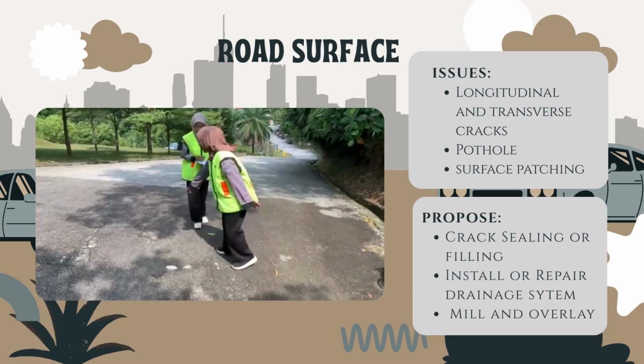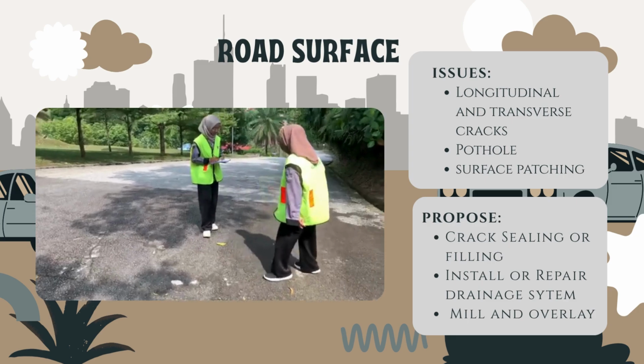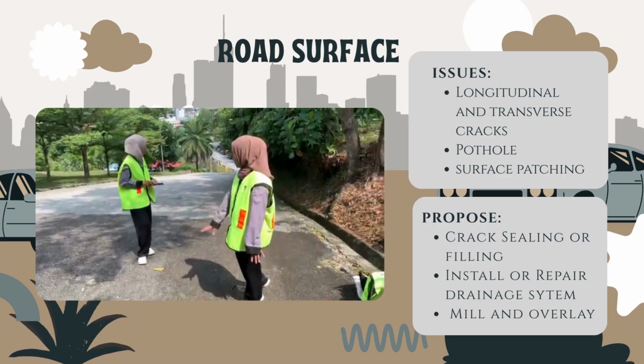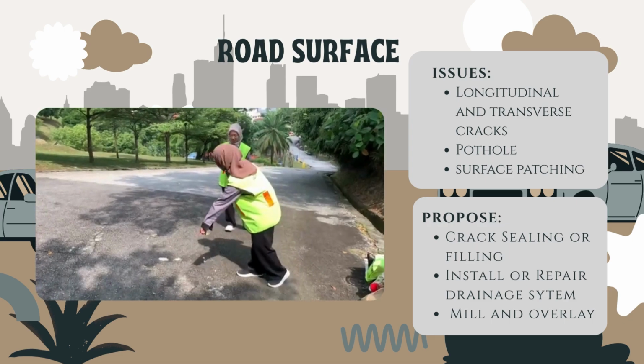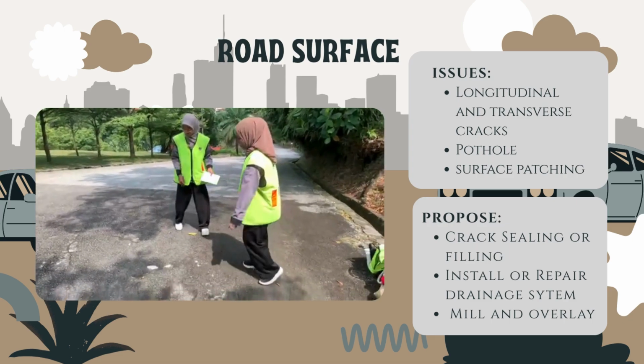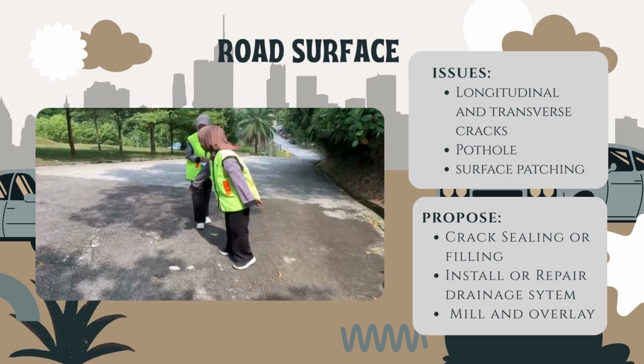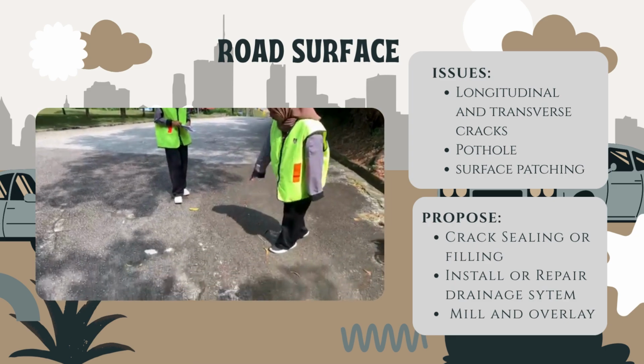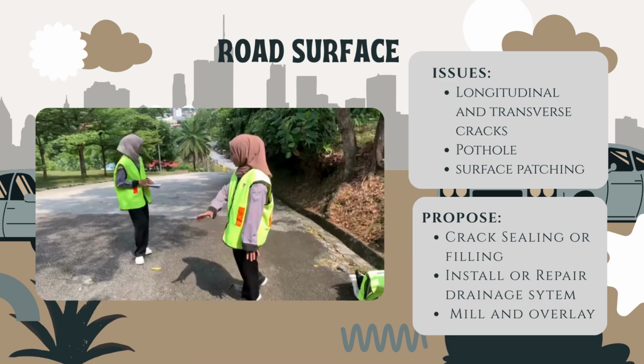The first issue is longitudinal and transverse cracks. The cracks form either in the direction of traffic, longitudinal, or across the pavement, transverse, usually due to temperature variations, poor joint construction, or aging pavement. It is recommended to use rubberized bitumen or sealant to seal cracks and prevent water infiltration.